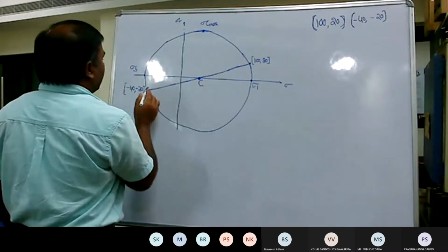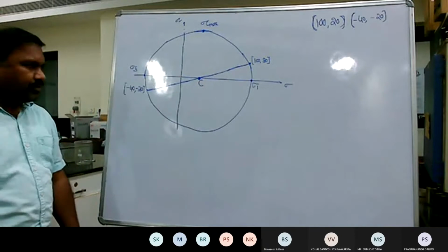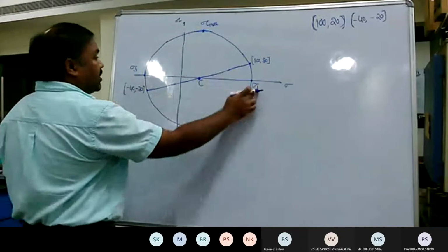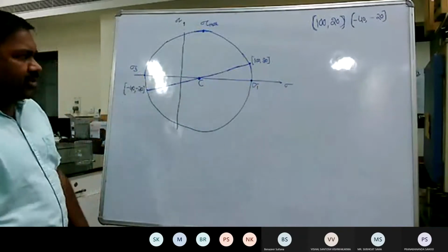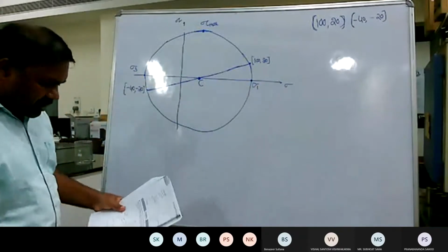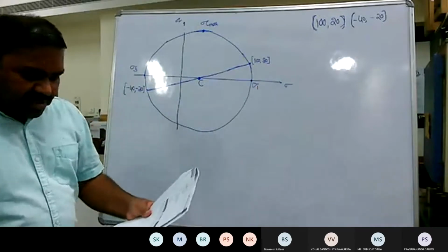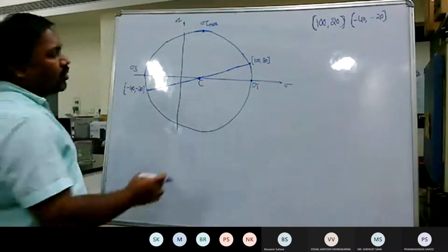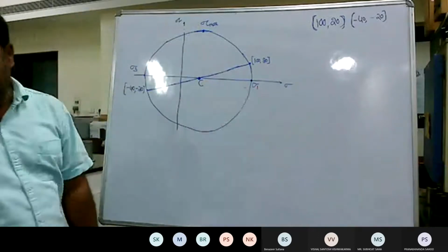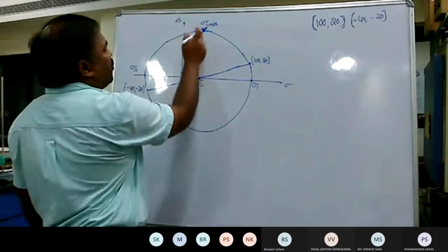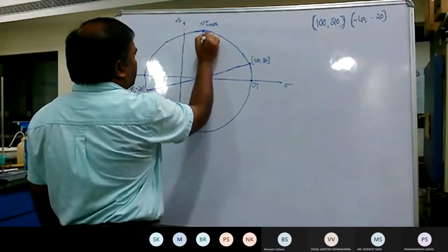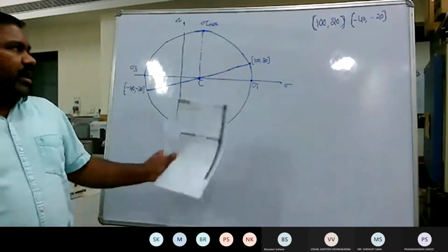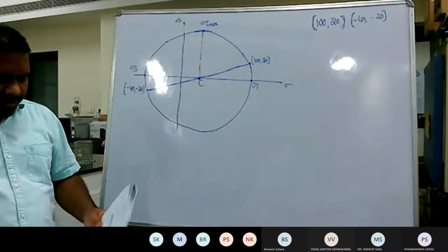So this is the horizon. So maximum principal stress sigma 1, so the major principal stress and the minor principal stress, that is sigma 1 and sigma 3. Now what has been asked? The magnitudes of the major and minor principal stresses. This we can now determine when you draw it on a graph sheet. Similarly, identify the topmost point. That would give you the maximum shear stress that is acting on the element.